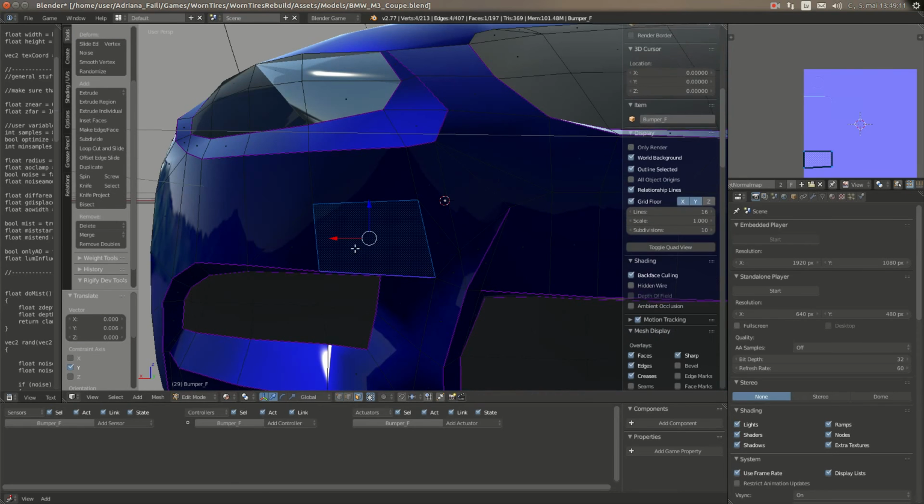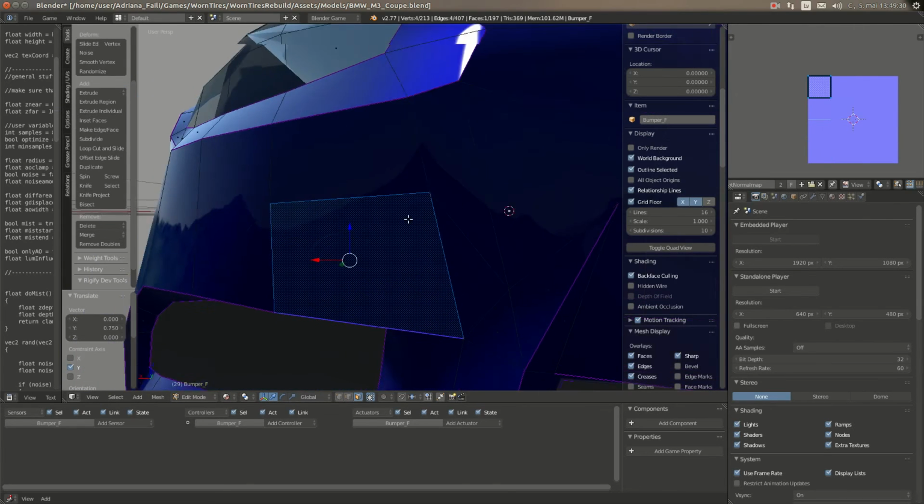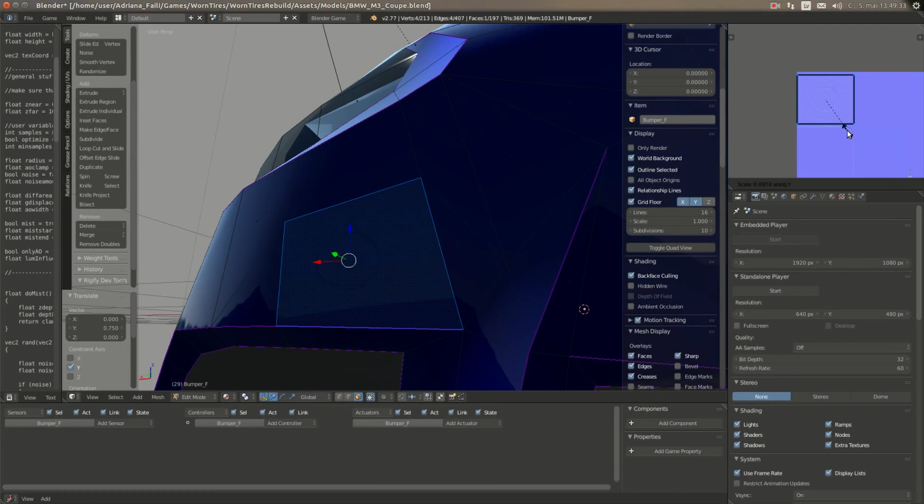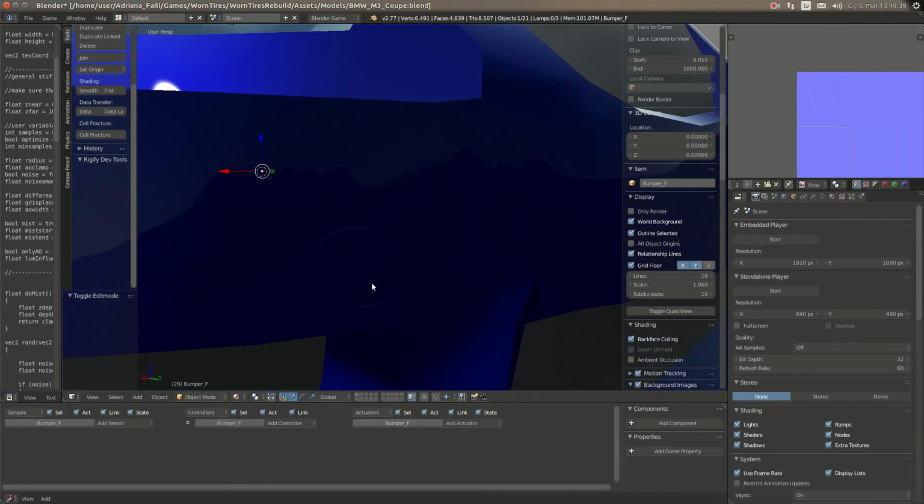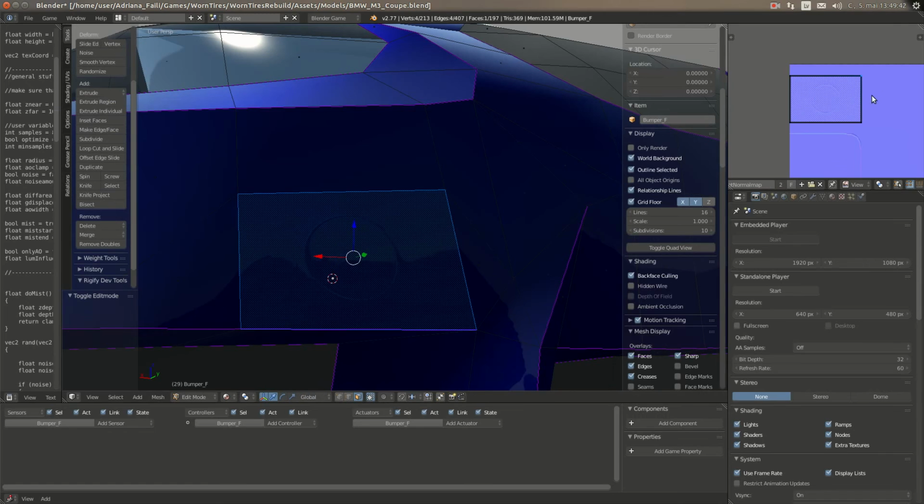Okay, and now let's select both of them. Reset scale 0.25, GX minus 0.375, GY minus 0.375. And now select this individual face, GY 0.75, and now scale Y, and just scale down until you get a nice looking circle here. You see, you must also match the form, the shape to the real detail, meaning this goes up and in like that.